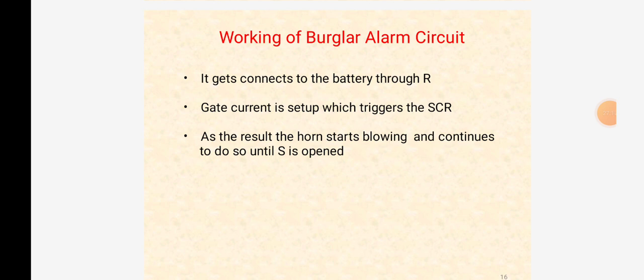In this, an emergency lighting system which contains a 12-volt battery at full charge switches automatically from AC mains to the battery when AC mains voltage gets interrupted. The transformer and the two diodes D1 and D2 form a full wave rectifier providing suitable DC voltage.